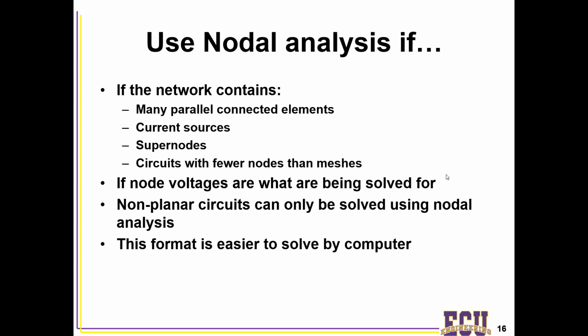In general, if you have fewer nodes than meshes, that's the technique that you want. And if you have non-planar circuits, mesh is off the table, but you can use nodal analysis. Oftentimes nodal analysis is easier to solve by computer, but we can do nodal and mesh in MATLAB with our modern computational tools, so that's no real big deal.